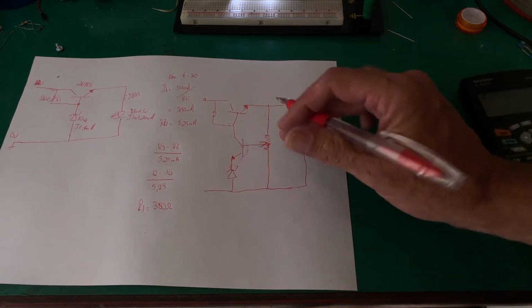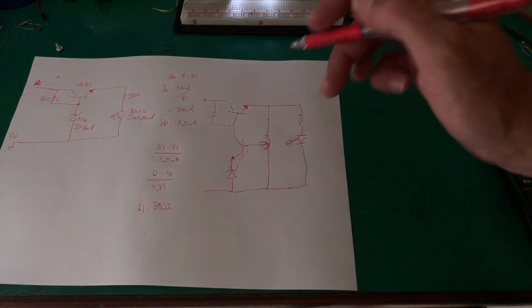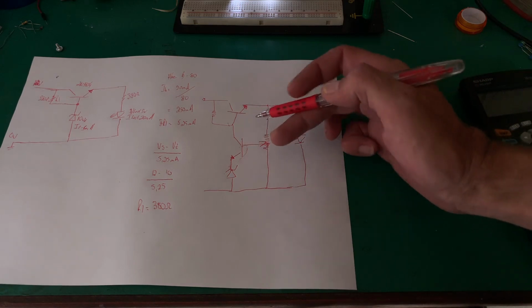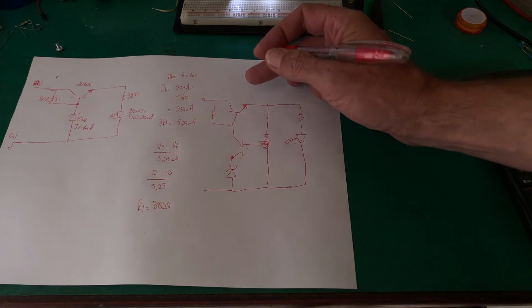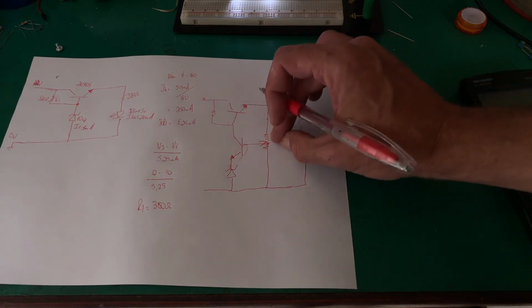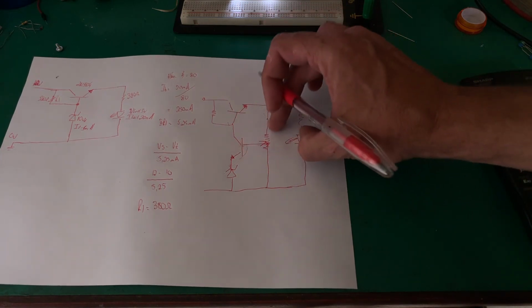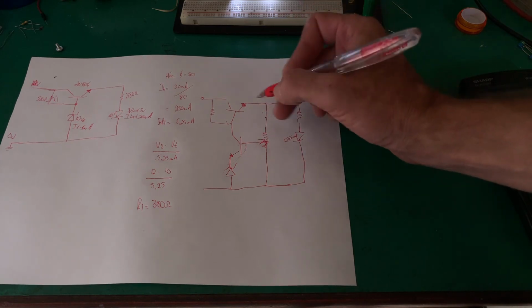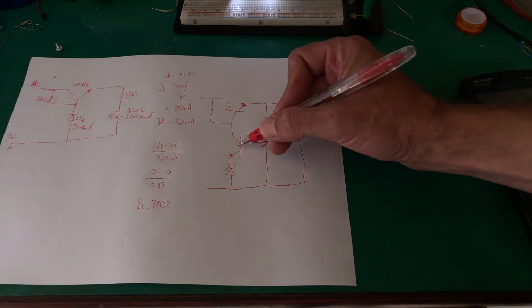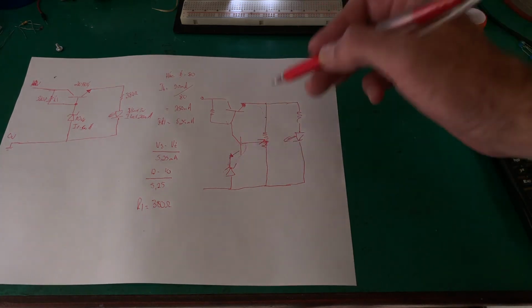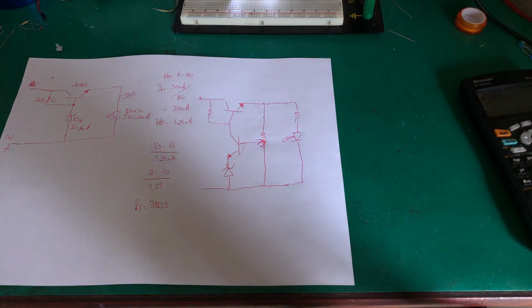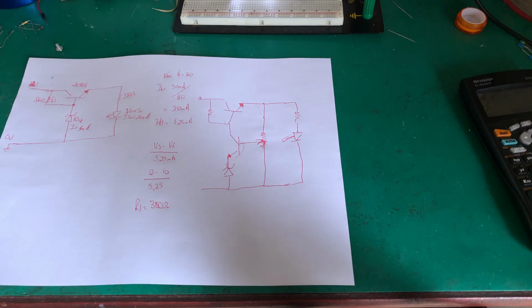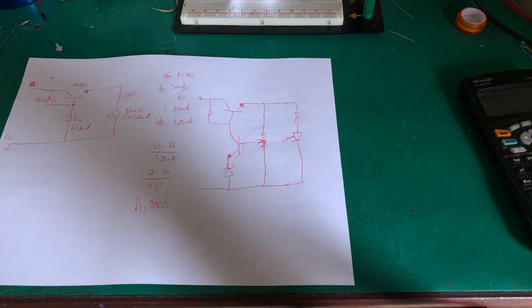Again, because we're adding the feedback, remember the transistors are acting in the active region, they're not on or off, they're conducting more or less. So this transistor is adding feedback from the output, adding a proportion of the output voltage back into the circuit to help this transistor. Nothing very fancy, but it works like a charm.